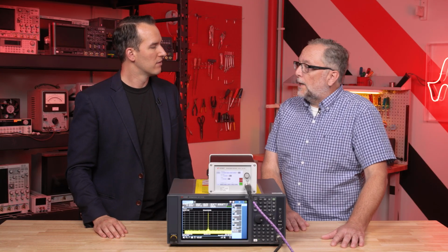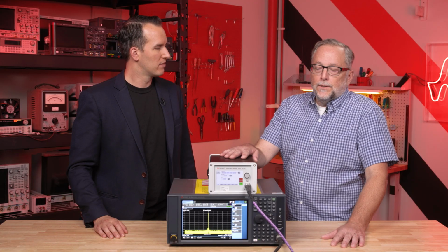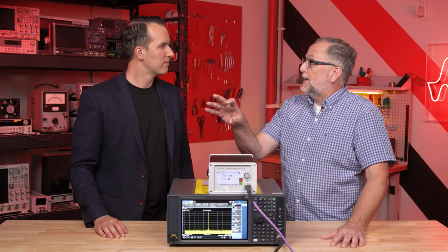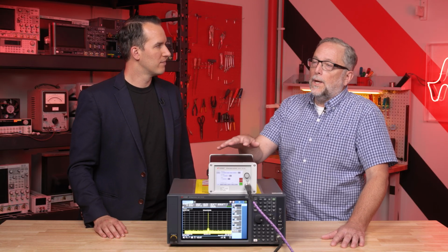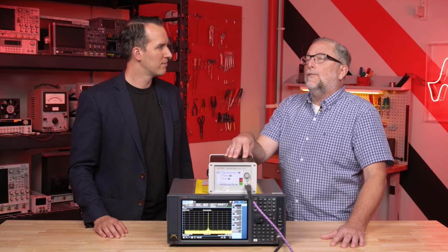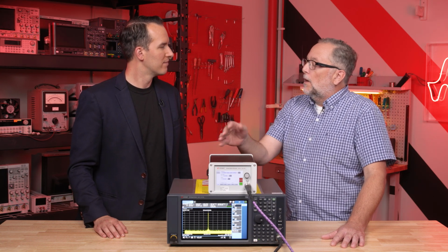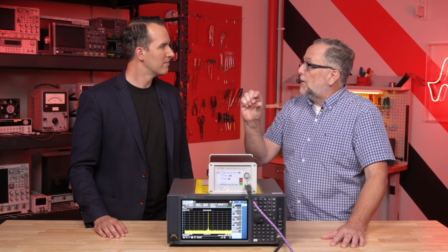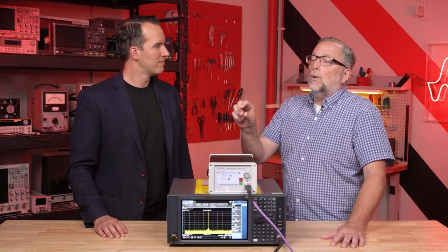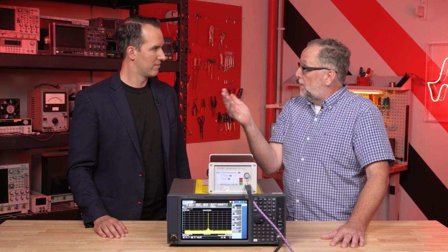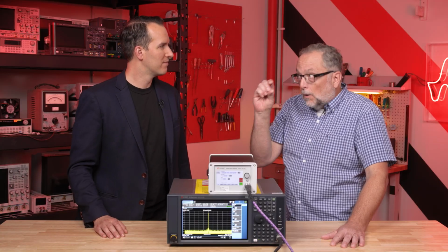Sure. It's a great question. When engineers are using signal generators to test their devices, they want to test the capability of their device itself. They don't want to be worrying about what is the contribution of the test instrument to their device setup. If you have an application like radar, where they're dealing with very low power radar returns in their receiver, you don't want to confuse any distortion products that are feeding through from the generator with your other signals of interest that are also small.